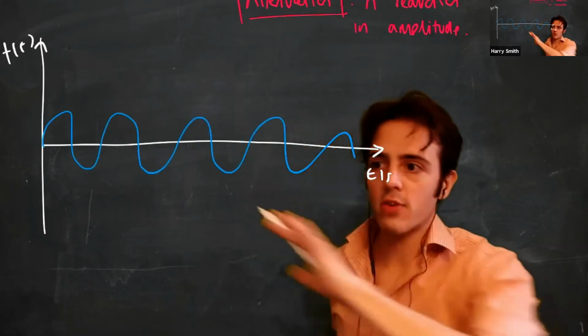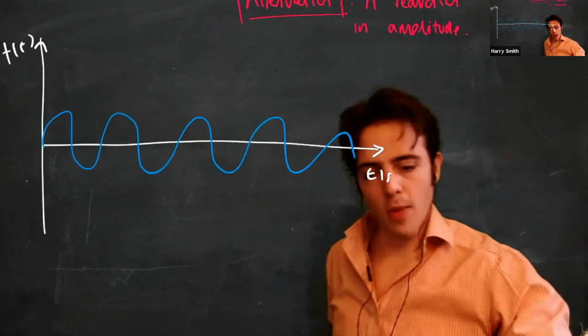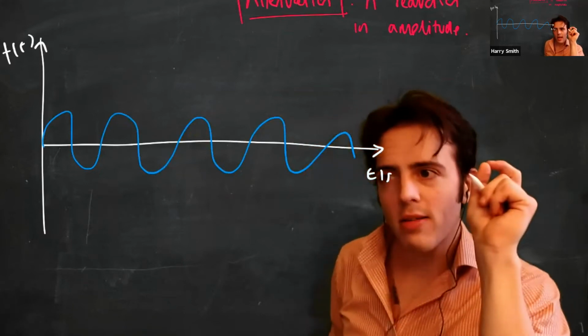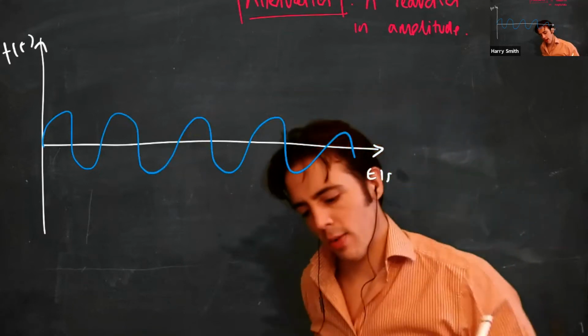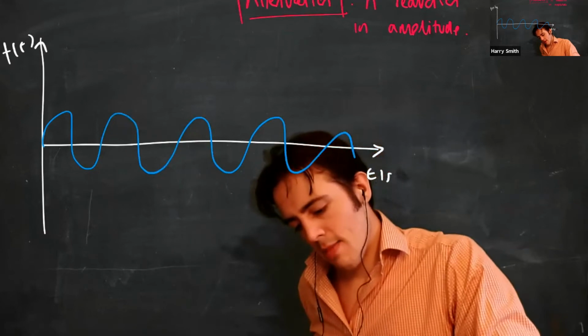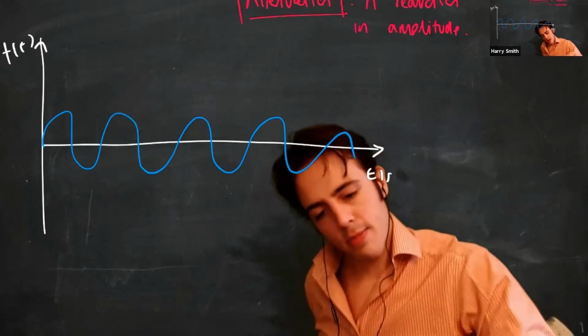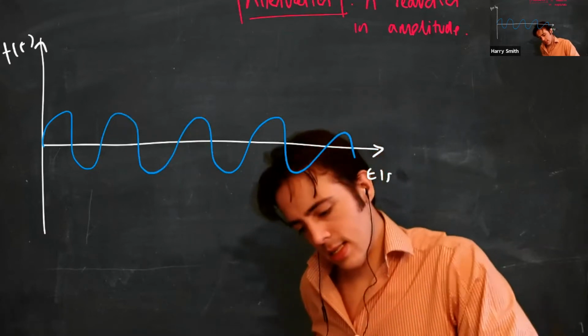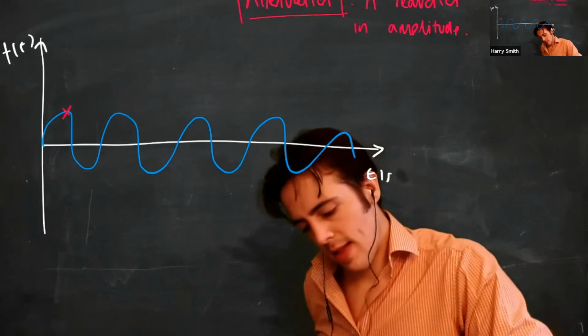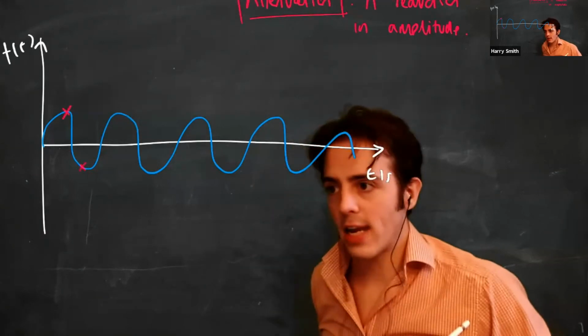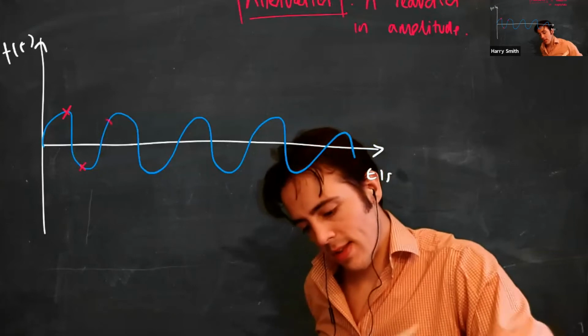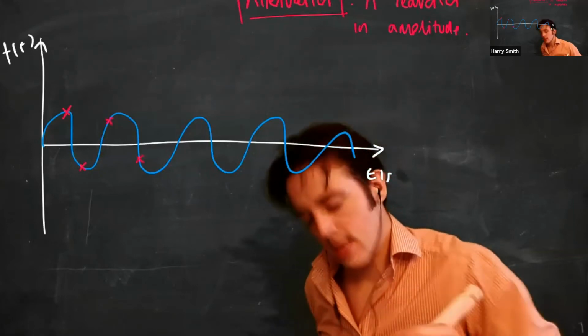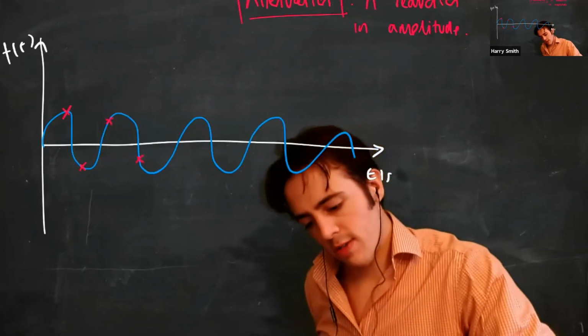Okay, so pretend I've got a signal that's a perfect sine wave. If we're sampling just slightly higher than the Nyquist rate, let's say my first sample is taken perfectly at the peak. This next one is going to be slightly ahead of the trough. This one's going to be slightly behind the peak, slightly even further behind the trough, and so on.